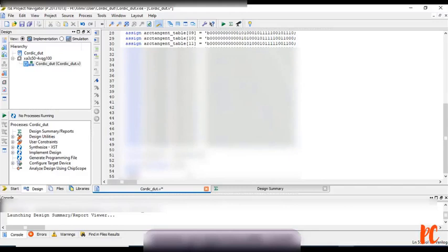So case I am declaring quadrant with respect to a 2-bit representation, 2'b00 followed by 2'b11. Because no change is needed for these quadrant values, that's the reason I am keeping as 00 and 11. Begin.